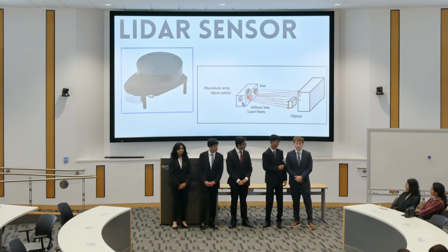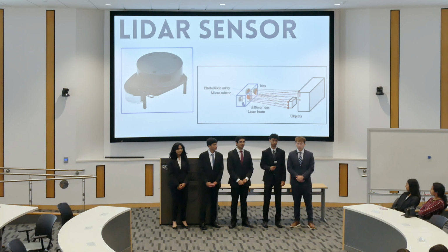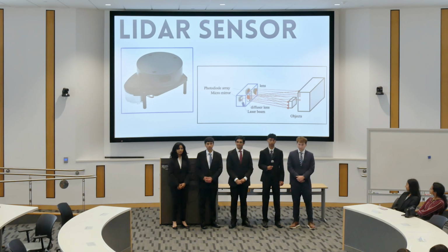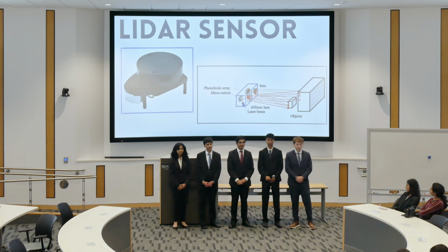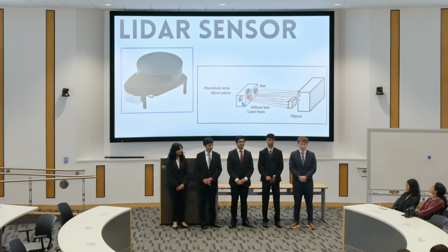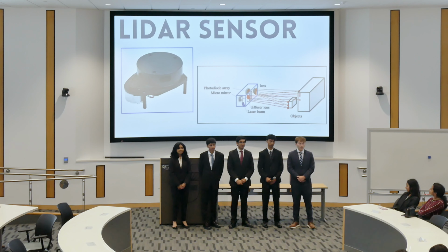In order to locate potholes, we're implementing a technology called LIDAR. LIDAR is short for light detection and ranging, and simply put, it works by the LIDAR sending out a beam of light or a laser, having that beam of light reflect off an object and returning back to the LIDAR. The return value for this is actually a time, but using something called a backscattering algorithm, this time is converted into a distance value, which represents the distance between the LIDAR and the object that is reflected off.